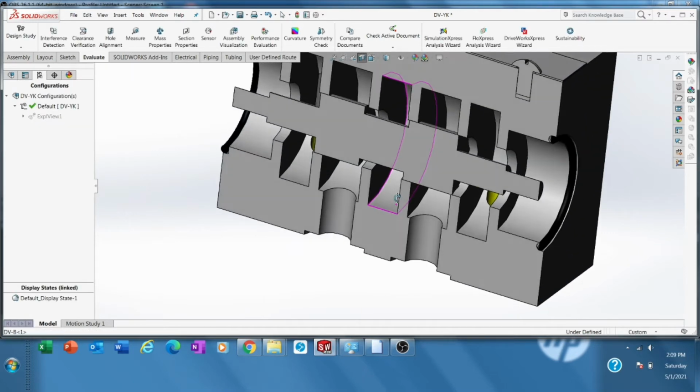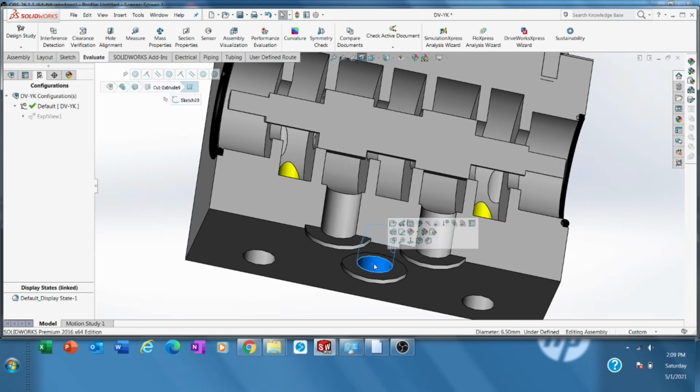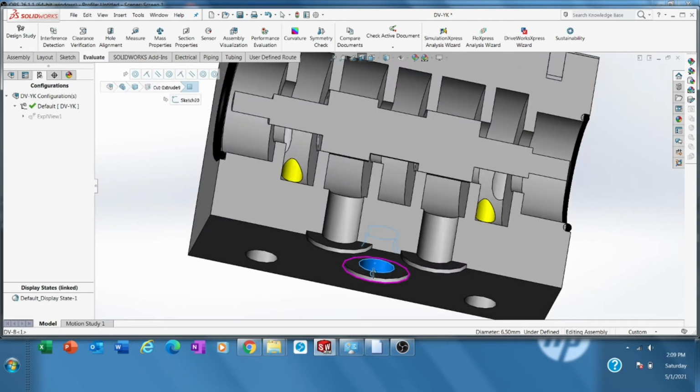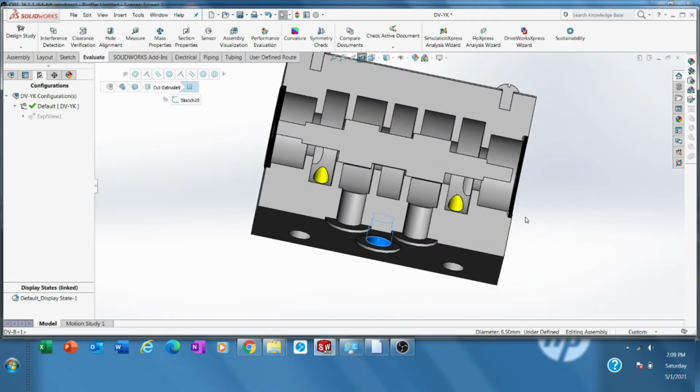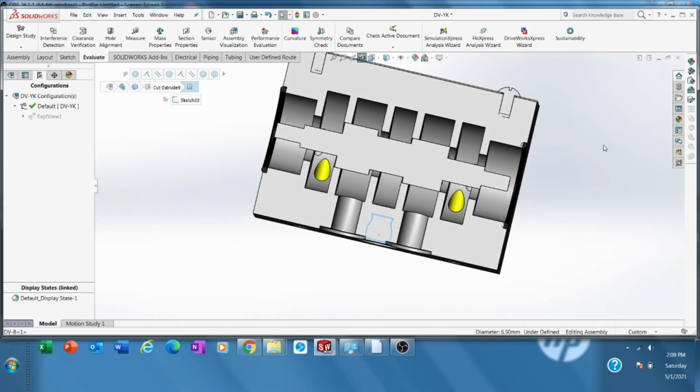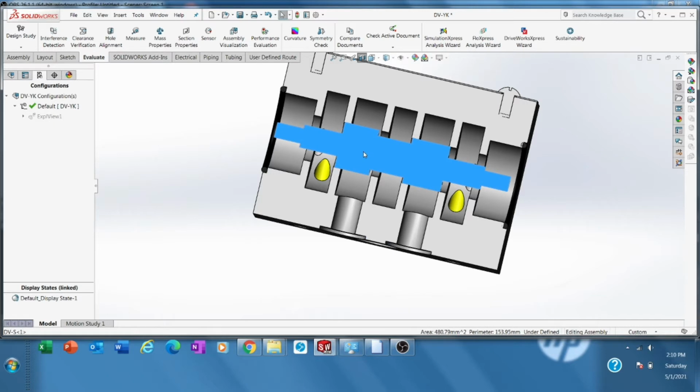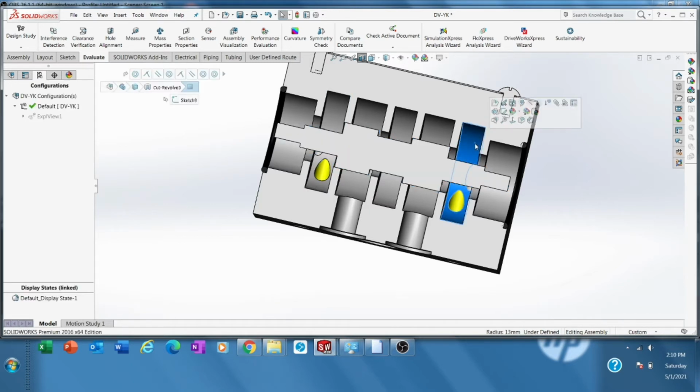So this is the P port, pump port, as I explained before. When there is no energization of the coil, left or right, the spool stays there, and the fluid pressure and the force become balanced left and right, with the pump still on. We call this a closed center, where the pump is not connected back to the tank.